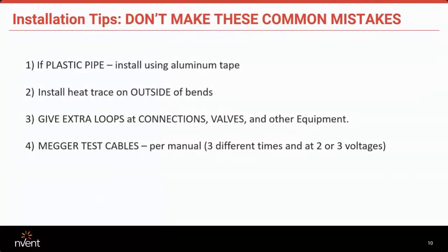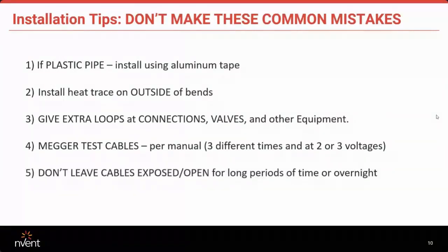Also take note that there are different voltages that you need to test at. Most cables are at 3 voltages, 500, 1000, and 2500 volts DC. There are some cables that only require 2 voltages. So again, refer back to your installation manual for those bits of information.